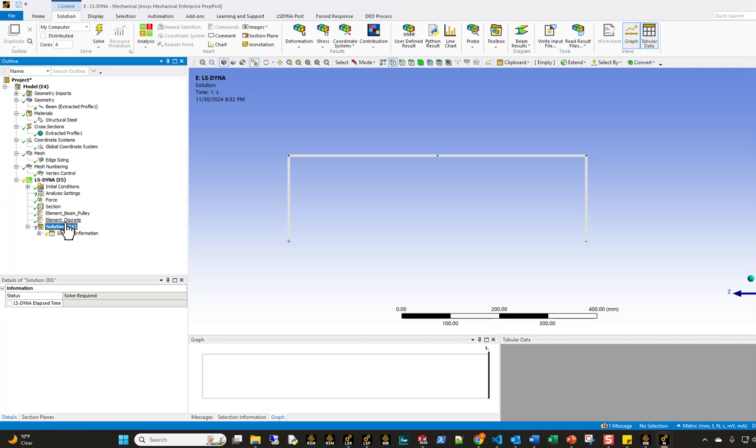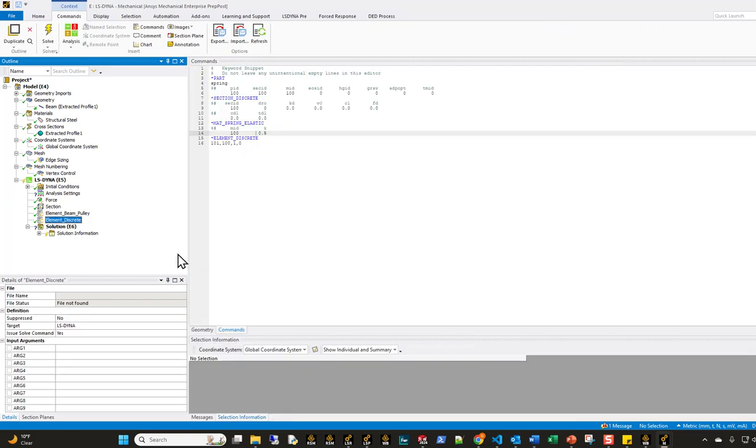So if that was hard to follow, just remember when you create a discrete element, you have to create a part, section, and mat, and then create a discrete element. And that discrete element is going to require you to reference a node value, which allows the spring to be attached. So if you assign two different node values here, you'll put a spring between those two nodes. If you do one of them with another one at 0, you're going to create a back to the ground spring, right? And that's all really what we have to do.